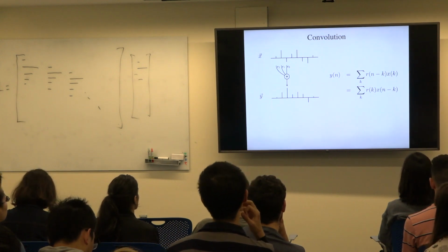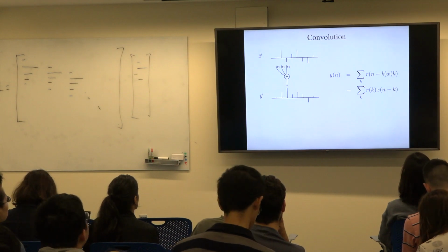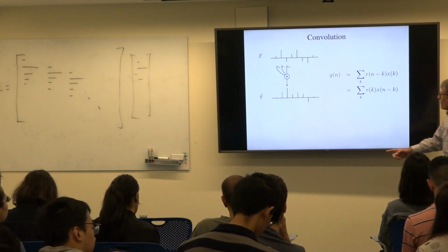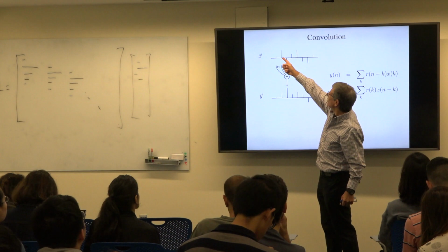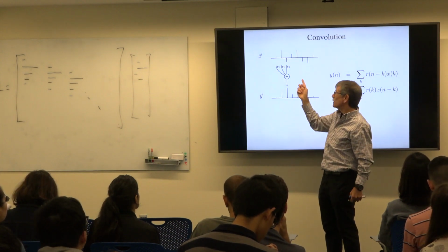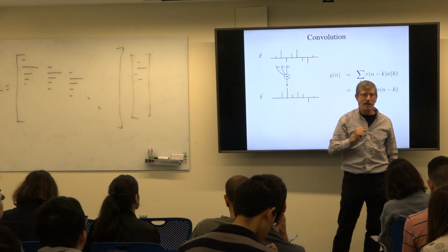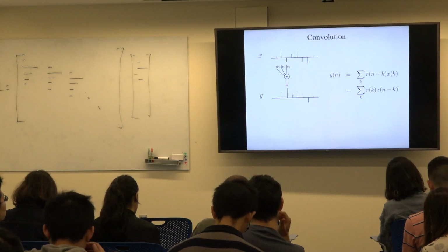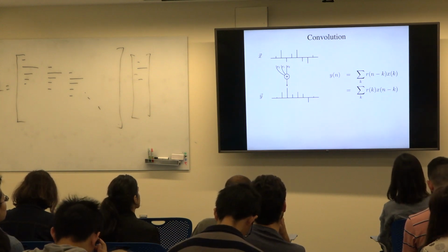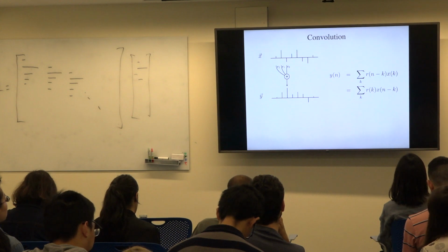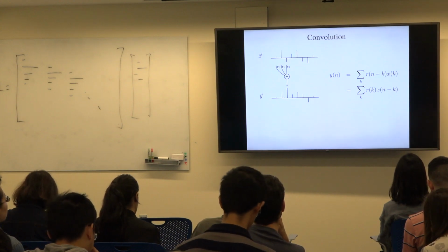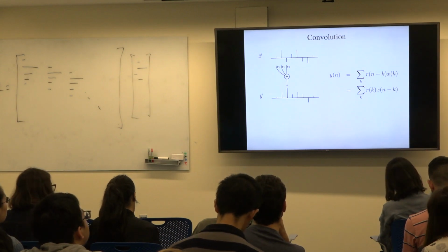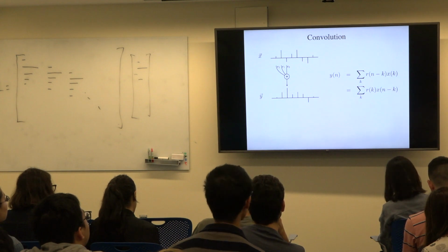And if the x-axis isn't time, this isn't important. But if we're going to treat the x-axis as time, my output now can depend on the input now and the input in the past, but can't depend on the input in the future. So this particular slide is written specifically to be causal. If the x-axis is something else, if it's space, that doesn't have to be true. But for time, if you're going to write a linear shift-invariant system, its impulse response, when you kick it, the output can only happen in the future. It can't create outputs in the past when you kick it now. If you figure out how to build such a thing, please tell me. We can all get rich together.